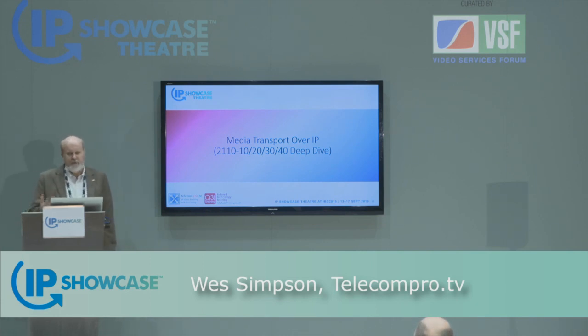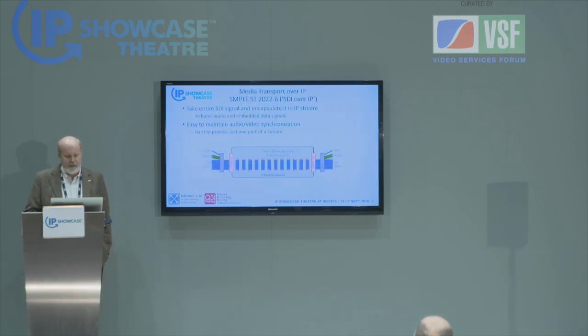So one of the first things I really want to make sure that we understand is the big difference between taking an entire SDI signal and transporting it over IP, which is absolutely allowed. We have standards for it. It's called ST 2022-6. We do call it SDI over IP. And what it does is it takes every single bit that you would normally find on a coaxial cable and allows you to transport that intact over an IP network.